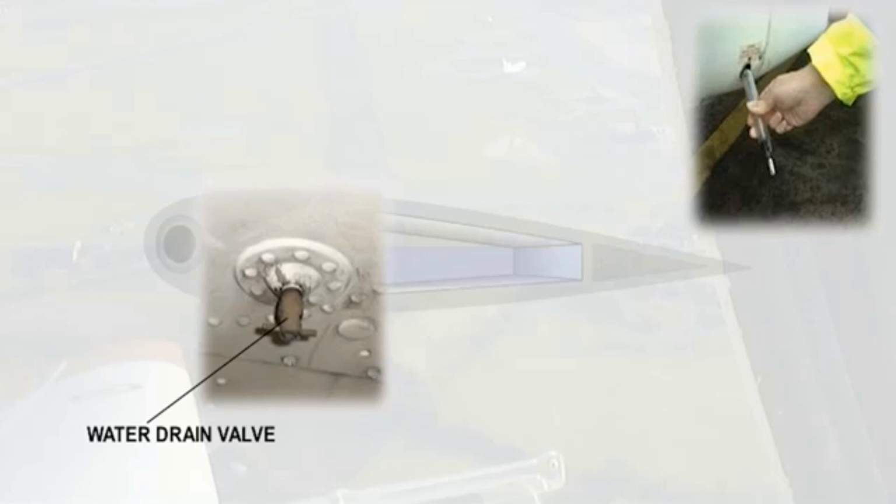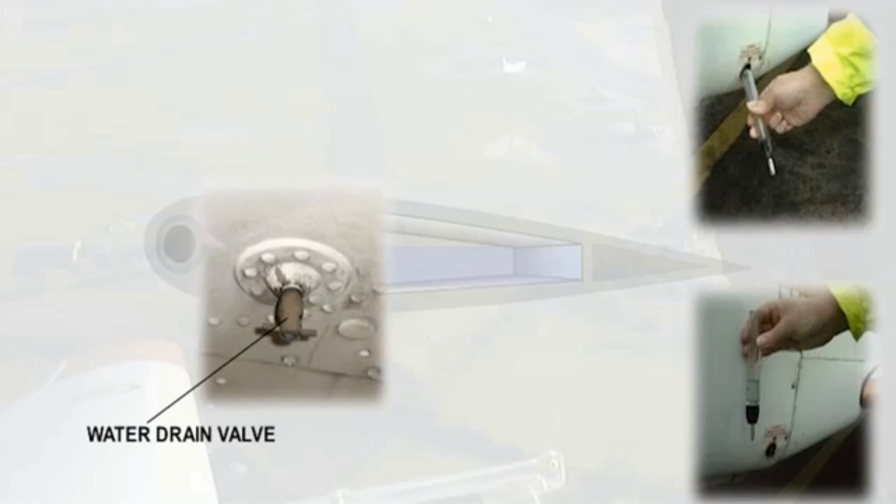After draining any amount of fuel, always ensure that no fire hazard exists before starting the engine. After using each drain, always ensure that it has been closed completely and that it is not leaking.